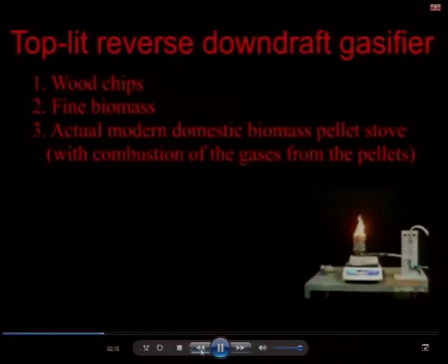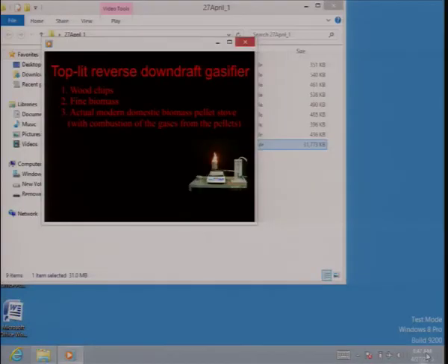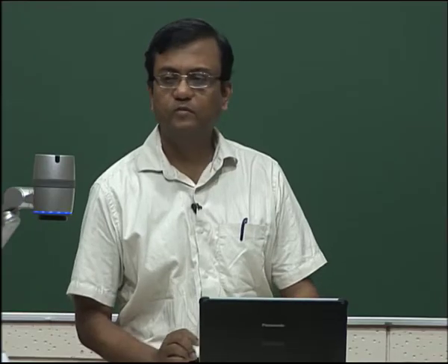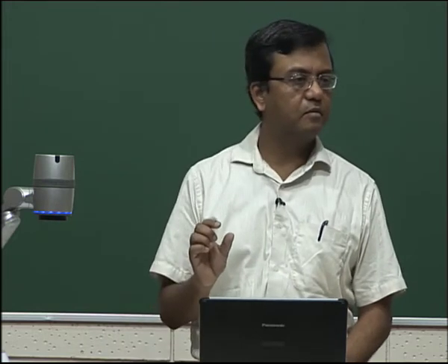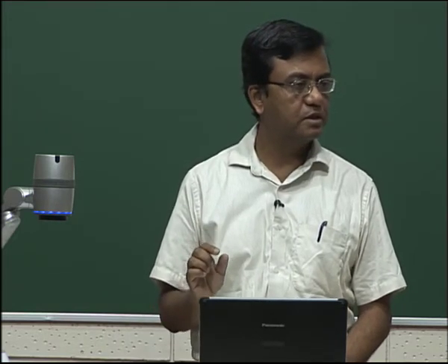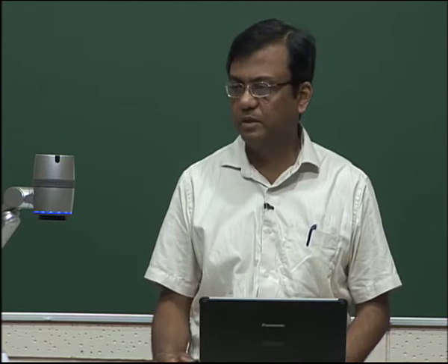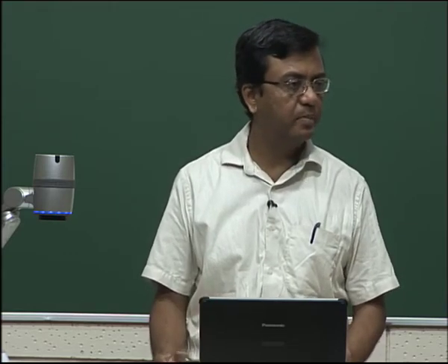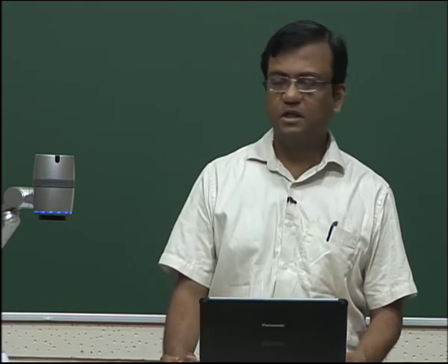All right, I think this is sufficient. This is just to give you a visual picture of how that combustion process looks like. So one thing that you will remember from this is that char combustion is actually more like the glowing combustion, and the flaming combustion is the volatile matter combustion, when you get a visible flame around the particle. This was of course a stationary particle.